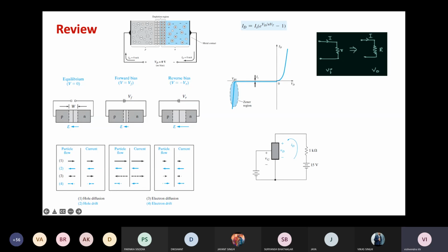One is when the current is transferred from a low resistance part to a high resistance part, and second is by having this kind of black box device which has IV characteristics like this, in which the current between two terminals, as a function of the voltage across these two terminals, can be controlled by a third terminal, which is essentially the gate terminal. A small change in the gate voltage can result in a large change in drain current, or the current across the two other terminals, and then this device can work as a switch and as an amplifier.